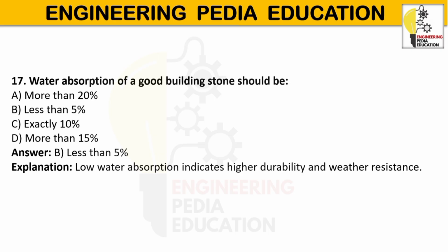A good building stone should have low water absorption, should not exceed 5% of its dry weight after 24-hour immersion. Low water absorption increases durability, reduces weathering and frost damage, and prevents dampness and deterioration.